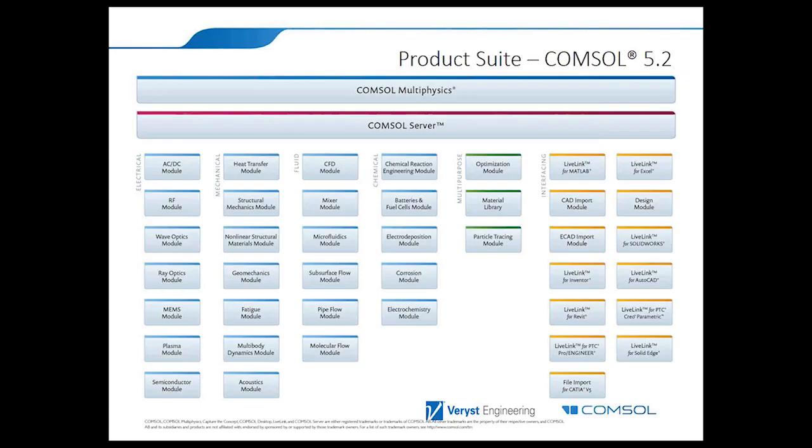And the COMSOL Server, I wanted to point out, has the functionality of COMSOL Multiphysics, but it doesn't have the user interface that you would use to set up the app or the model. It's what you would use to actually host the application so that someone can run it. But then someone would ultimately access it through a COMSOL Client for Windows or through a web browser. And so I just wanted to make sure that you knew about that as well, pertaining to not only what you would need to set up apps, but also what you would need in order to give someone else access.